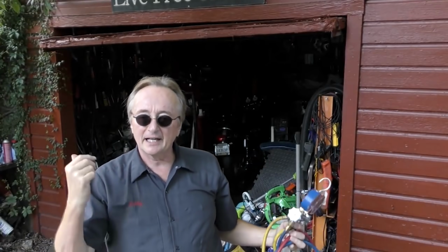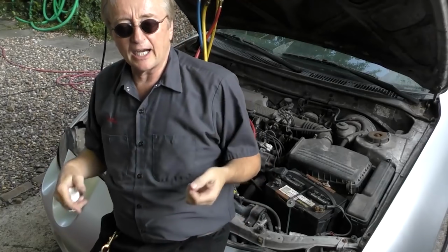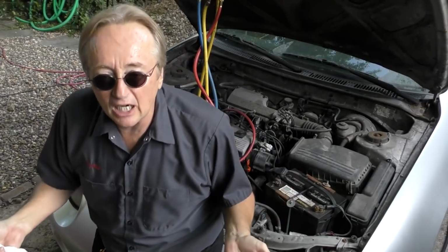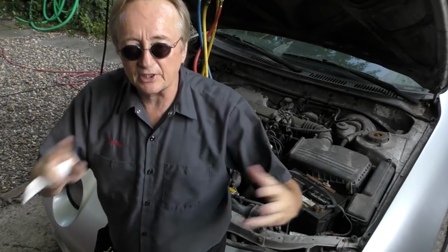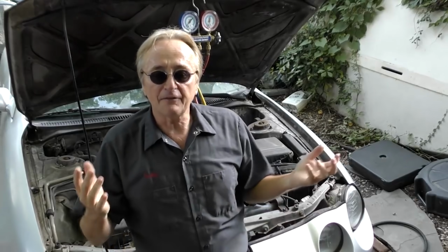Today I'm going to talk about a common car air conditioning problem and how you can fix it. The problem is this. Say the passenger side is blowing cold air, but the driver's side is not blowing cold air. Now in an old car like this 94 Celica, it's a simple air conditioning system. It doesn't have dual controls or anything. It's got AC, you turn it on or off. Then it's often a very simple problem, just being low on refrigerant.